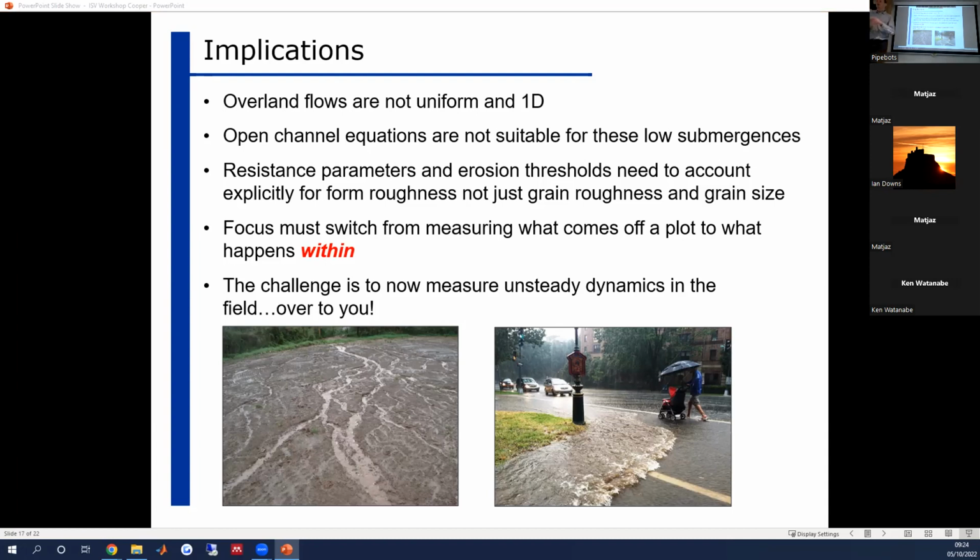Yeah, so we did it for these particular tests at the beginning and the end because we didn't want to stop the rainfall event, as that could potentially influence how the topography develops. But in some separate tests, we did do exactly that. We did much longer events of 60 minutes, and every 10 minutes we did those microtopography measurements, so we could see how that developed through time.